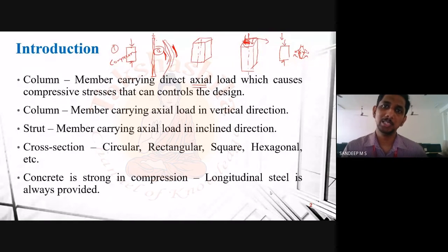So steel is actually good in taking compression as well as tension. Even though concrete is very good in taking up compression, suppose we have a very large load, what will happen? The dimension of the concrete column required will be very high. So in order to reduce that, we can provide some longitudinal reinforcement inside this, so that this steel will help in taking some of the load.